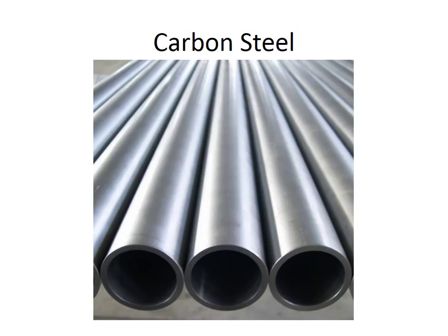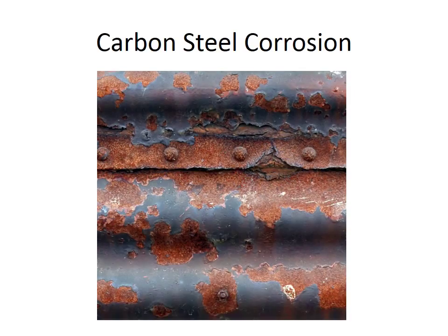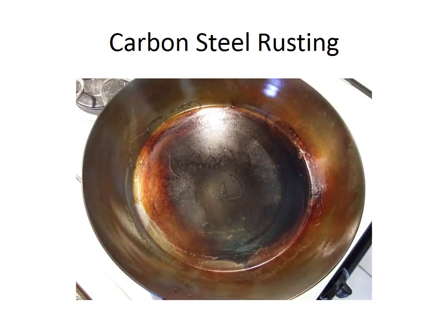Carbon steel used to make up a large portion of the low-temperature thermal desalination plant, the evaporation phase in particular. It was readily available and an already well-known material, which made it easy to use. However, carbon steel was also known to corrode quickly. The corrosion and rusting of the carbon steel mainly occurred because of the nature of its function. The presence of oxygen, carbon dioxide, chloramine, and the heat in the salt water evaporation process would then initiate corrosion cracking of the carbon steel.